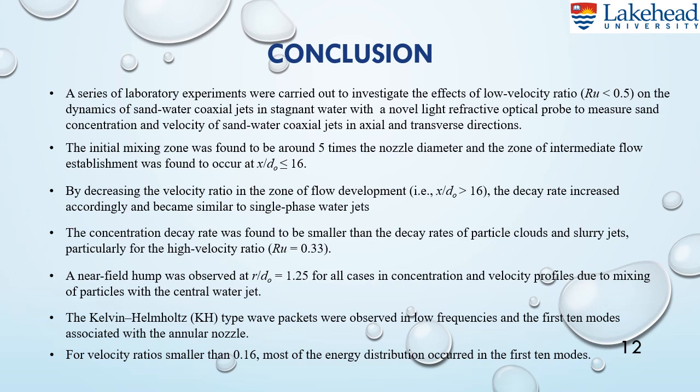The concentration decay rate was found to be smaller than the decay rate of particle clouds and slurry jets. And also a near field hump was observed at r/D equal to 1.25 for all cases of concentration and velocity profile due to the high mixing of particles with the central water jet. And also spectral analysis and SPOD measurement were employed, and it was observed that they can be characterized by Kelvin-Helmholtz instabilities, and mostly the energy is stored in the first 10 modes.